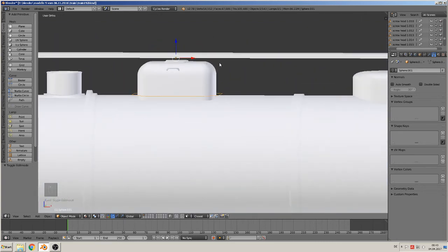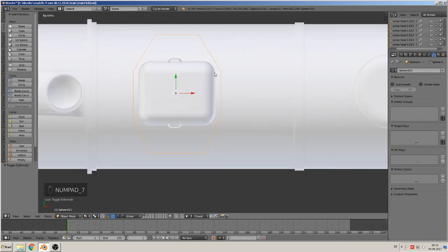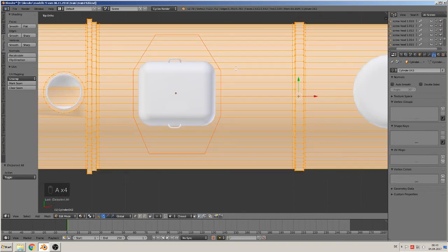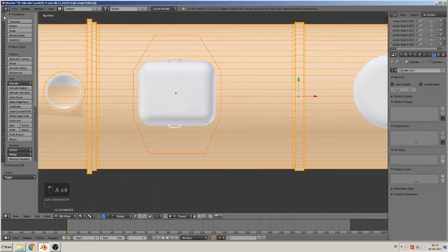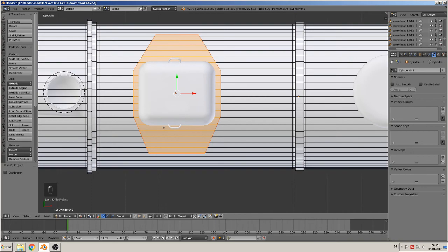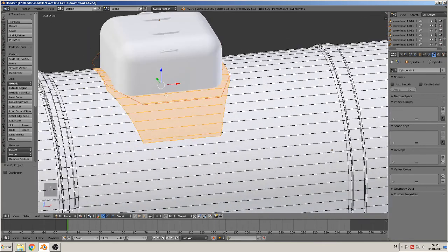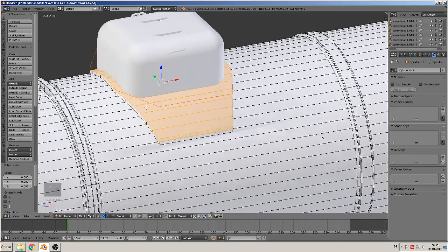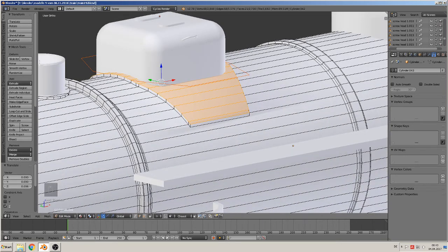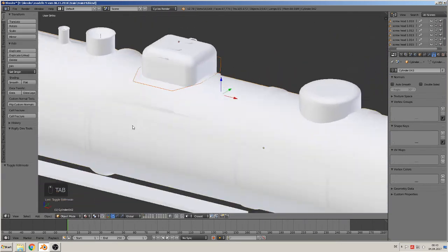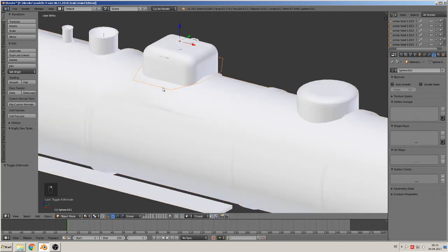So we're near on it. Top view. Mark first that thing, then the other. Now edit mode, mark all, tools, knife project. We have it. When we now extrude it, we have that rounded thing there. That is good. Good. We can move that here to the third layer.